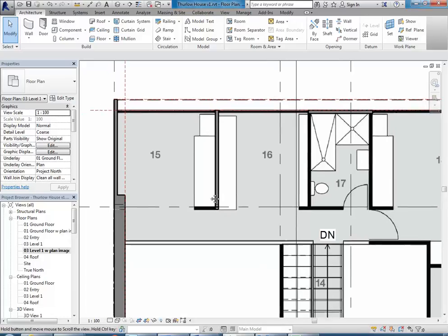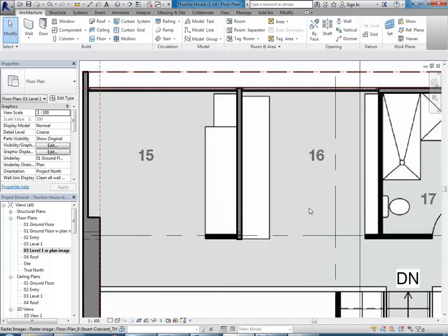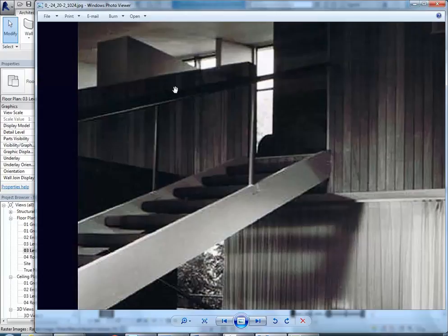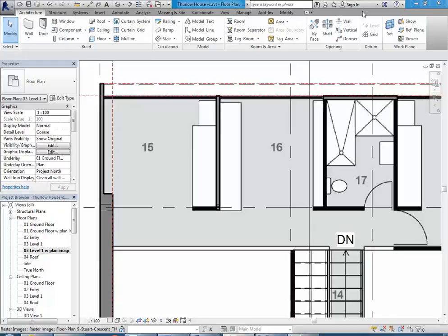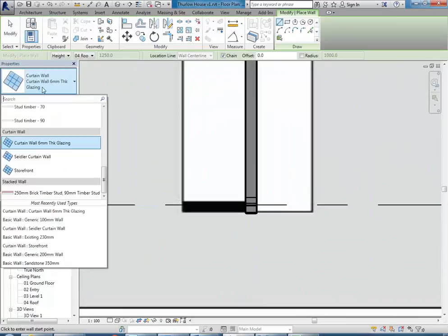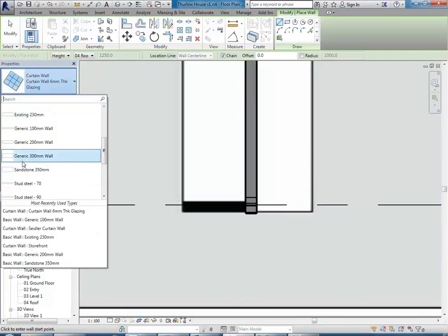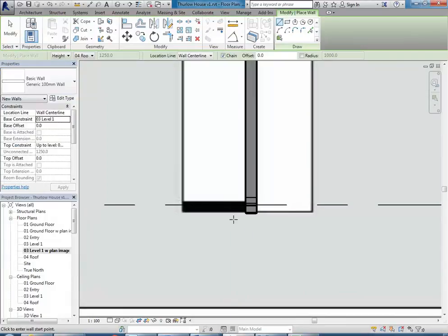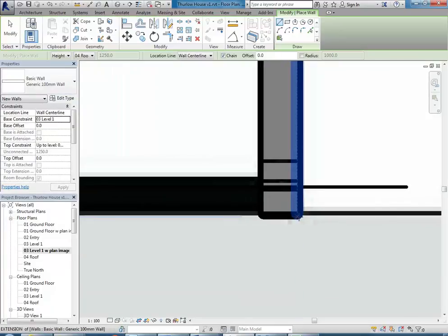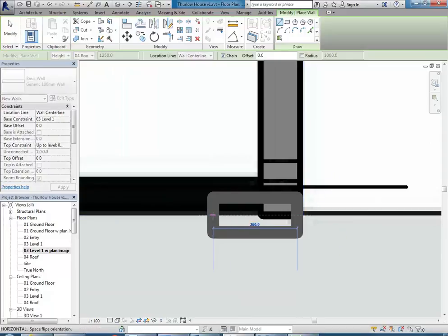Okay, so anyhow, you can work that out as you draw your walls in, and that should make it easier, in fact, if it's open plan. So you've got a wall there wrapping around, and so just use the generic walls to lay it out. We'll put the doors in afterwards, and so the main tip I can give you there is that you just want to ignore the openings.